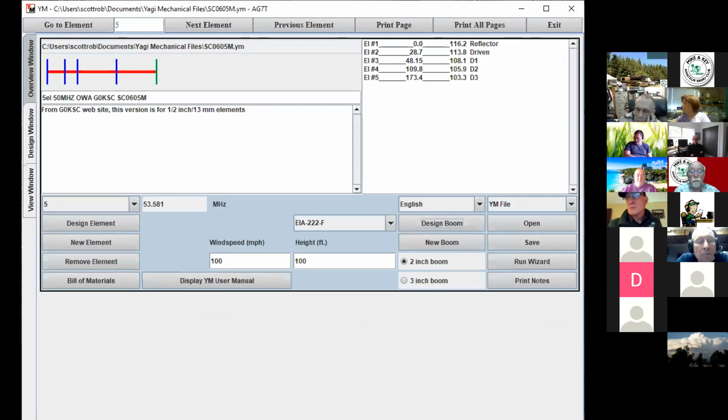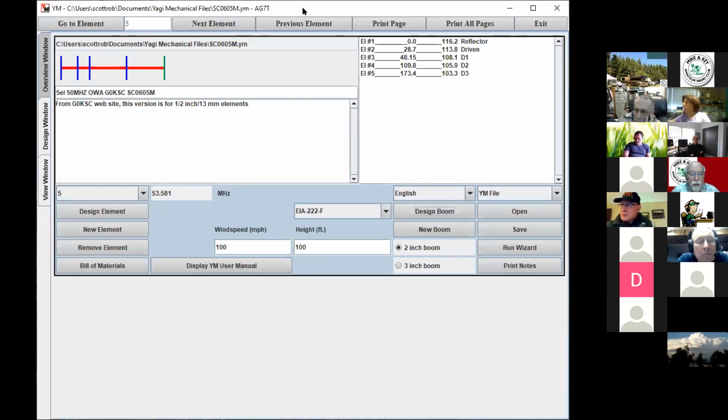So these are all fine for putting up. Now, if you were over close to the coast, up in the Skagit, you will hit those 90-mile-an-hour winds. It's fairly common. I crank my tower down here when it gets above 55 in the Puget Sound area. But all of my stuff is good for 100 miles an hour, everything up on the tower. Any questions on this?